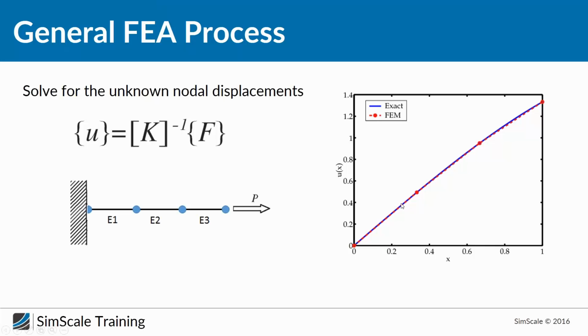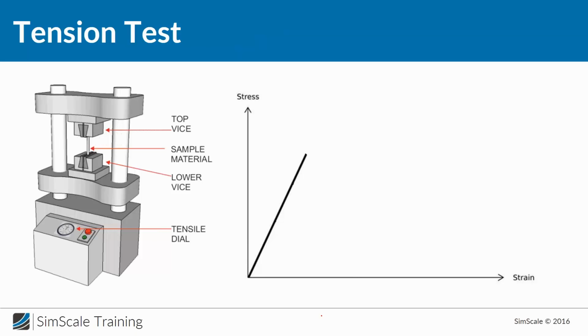And if you compare the results, you can see that there is a linear interpolation between these nodes if you have a larger model, and that is very important, because just imagine if you would only use one point, I hope you can see it, then you would have a larger difference. And in the end of the day, the accuracy of a simulation is massively depending on the right sizing of your mesh, the right density of these nodes. And I hope that this helped you to get a little bit of an idea about the background of FEA.